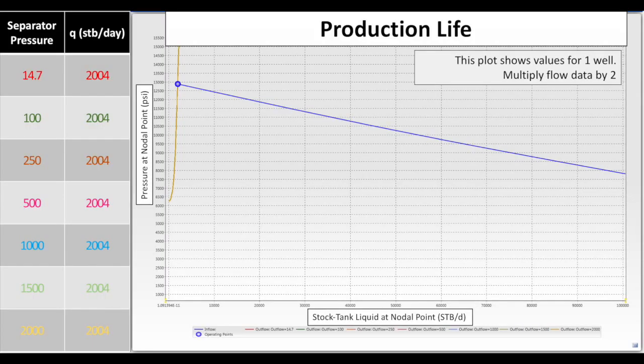In our calculated well, our separator was located on an offshore platform which was 82 feet above the surface of the water. The well stream fluids traveled a total distance of 12 miles from the time they exited the wellhead to the time they entered the separator. To make our simulator calculations easier, we used a sink within Pipesim to represent our 2-phase separator. While this was not the most practical method, and because we used a sink, we had to assume single-phase oil within our well stream throughout production.